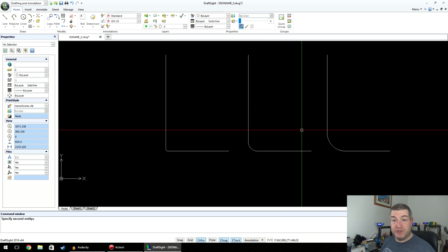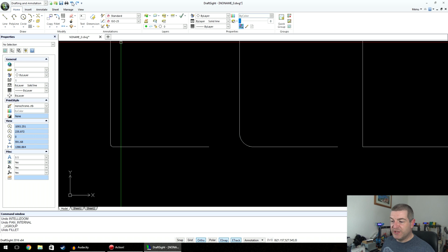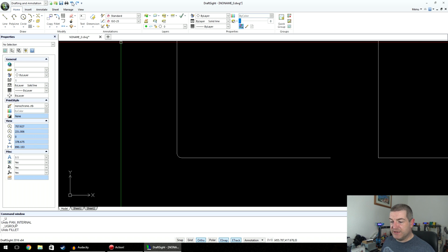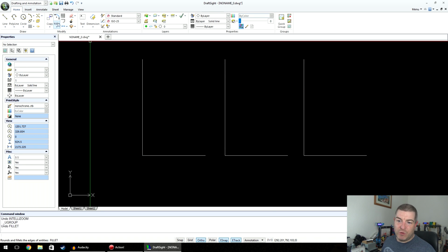Right, now I'm going to introduce you to another command. It's called undo. Everybody knows what undo is, but I'm going to point to it. It's there. So I'm just going to undo the fillets, and as you notice, it undoes all of the pan and the zooms as well. Right, what we're going to do is we're going to drop this down. We're going to look at chamfer.